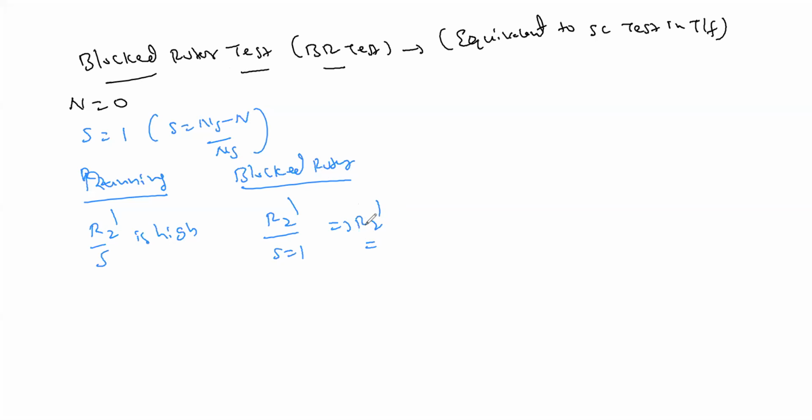Resistance कम है ना तो ज़्यादा करंट आएगा, लेकिन don't allow the more current to flow, just allow the rated current to flow. कैसे कर सकते यार? आप rated voltage मत apply करो, you apply some voltage such that short circuited rotor में अभी rated current जाएगा. उसके लिए हमको voltage कम करना पड़ेगा supply side. ठीक है? What is the equivalent circuit here now?